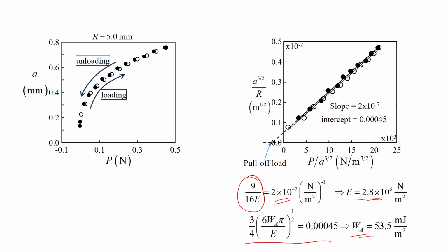This is a typical silicone with a somewhat modified glass surface, where hydrogen bonding and other interactions are not there. Dispersive interaction you will get very similar to it, maybe a little smaller. Now, what is interesting here is that the force versus displacement data in the loading cycle and the unloading cycle superimpose. So, what it means is that there is no hysteresis in this case. The work of adhesion during the loading stage and the unloading stage remains equal.